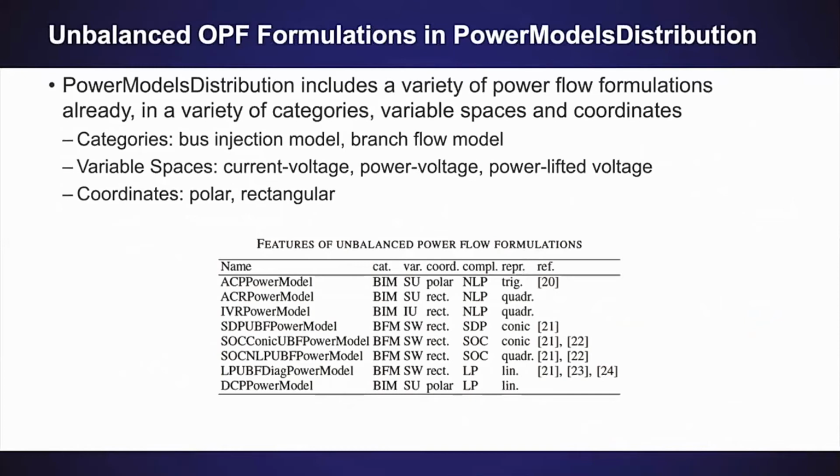In terms of the powerful formulations already included in PowerModels distribution, we have a nice set of formulations that include several nonlinear formulations, semi-definite and second-order cone relaxations, and several linear approximations, as you can see here in this table. These formulations cover several different categories, such as the bus injection model and the branch flow model, multiple variable spaces, such as current voltage and power voltage, and multiple coordinate spaces, like polar or rectangular coordinates.